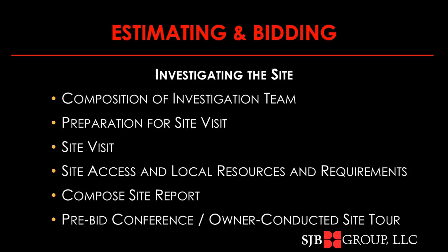So under preparation for site visit, we're going to study the plans and specifications. We're going to work up a preliminary construction plan, identify the approximate significant work, make some tentative decisions on some subcontractors, understand what the local material supplies are. We need to determine some equipment requirements. We need to investigate any legal and financial problems. And we need to start writing our questions to be answered by the owner site rep.